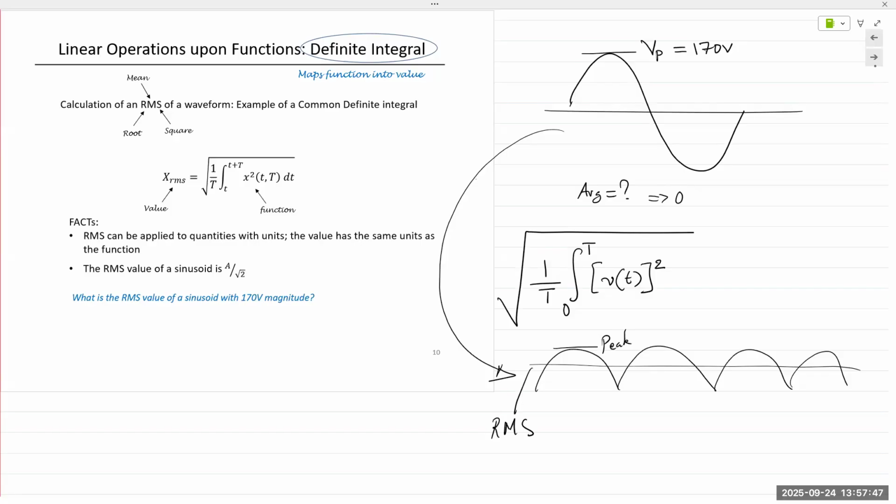If you're using a DC multimeter, AC multimeter anywhere in the lab, or you're referencing an experiment, if you have only one single value, that means it's referring to RMS. If it's peak, it will explicitly state this is the peak voltage or a peak current. Okay. Everything else is an RMS. If it says 440 volts AC, that's an RMS value.